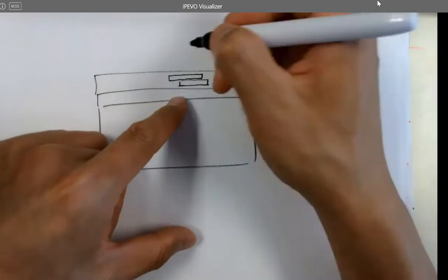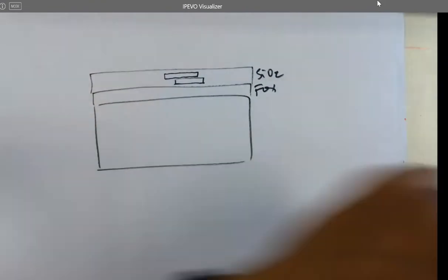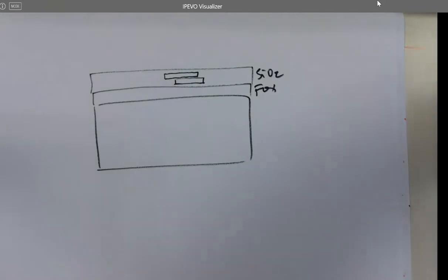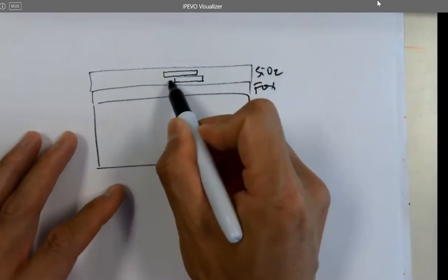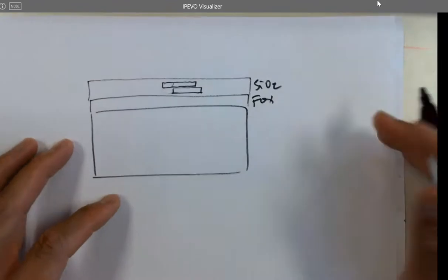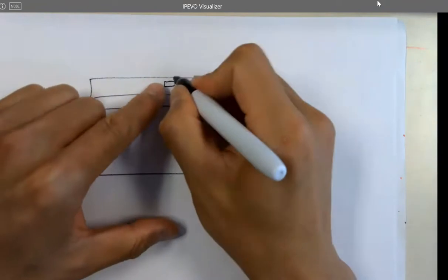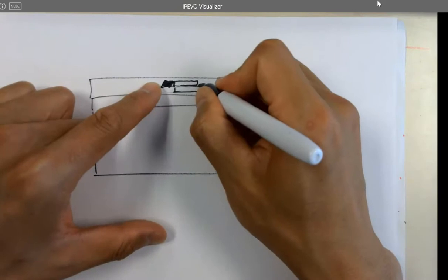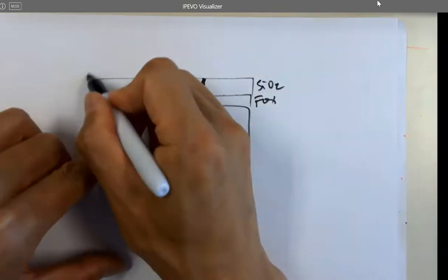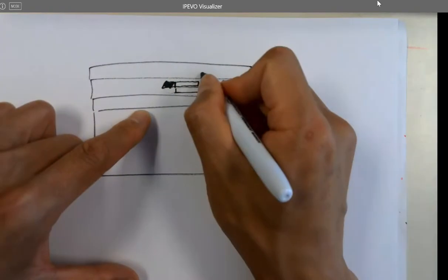Is that the right way to do it? All right, you don't have to. So are you actually using this part of the poly? No, you're only using the overlap area, right? So just stop here. Then what? Via the poly 1 to what? To metal 1, right? This is metal 1, right? You've got a metal 1.